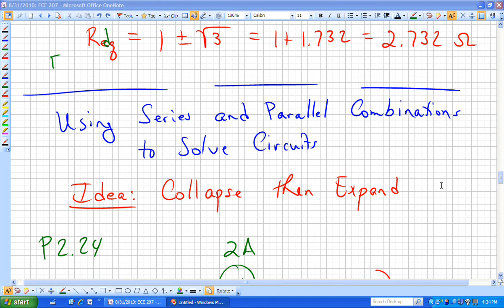If we need to know the voltage dropped across R2, you could say, okay, which way do you want it to go? How do I want to hook up my voltmeter? If I put my positive lead on 1 and my negative lead on 2, I'm measuring V sub R sub 2, and that would be V1 minus V2. If I knew V1 and I knew V2, which is what we will find eventually, then we could find what the voltage dropped across R2 is from left to right. Is that making any sense?